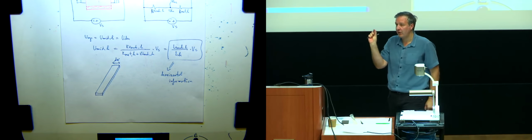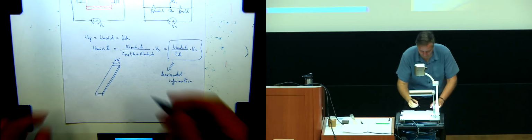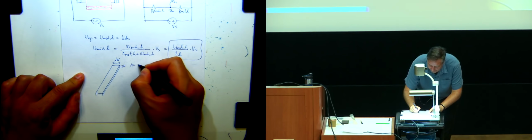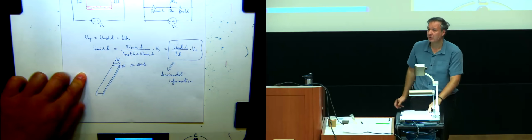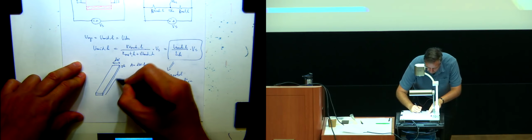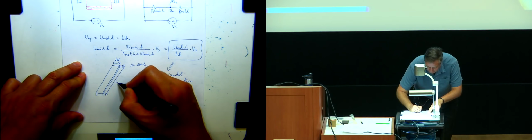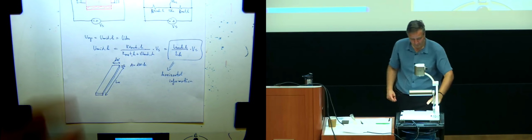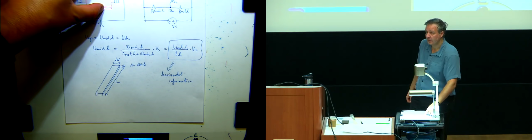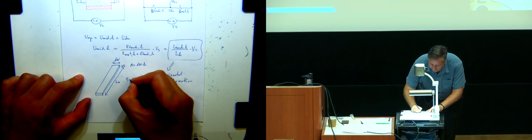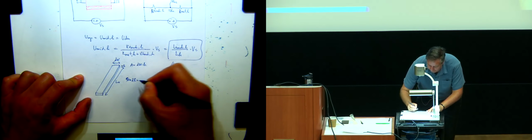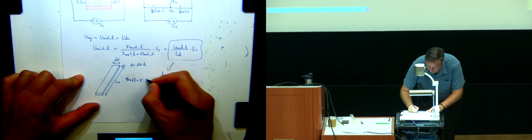This is a super small width, and let's call this some height h. So then my area is dW times h. My length is length vertical, the full height of the screen. Then the resistance of this, let's call it dR, will be rho times LV over A.